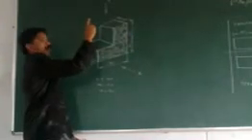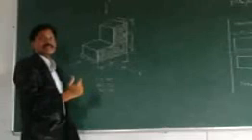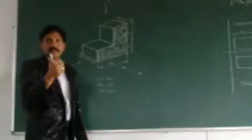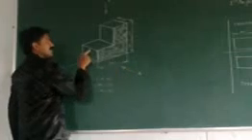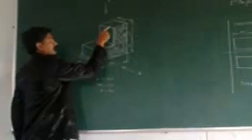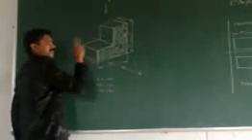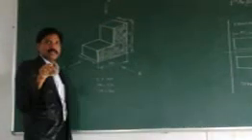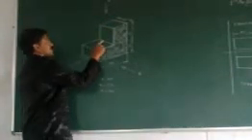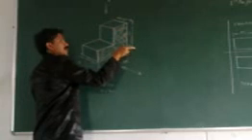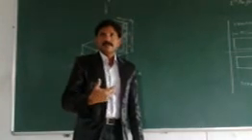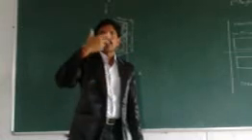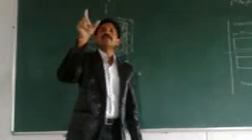Next, coming to the top view. What are the dimensions that we are going to concentrate on? Length and width. Here the length is 100 and the total width is 50. But there is a split. There are 1, 2, 3, 4, 5, and 6 widths. But when you observe from the top direction, you will get only 3 widths.